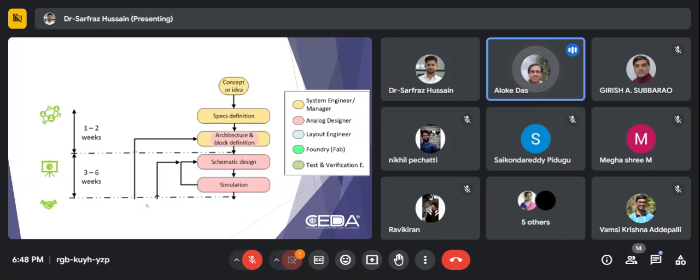And coming back to ADC, there could be a simple ADC, an R2R ladder kind of thing, or it could be a SAR. So if you can do a complicated A to D converter, do it. If you cannot, do a simple A to D converter. It may not be megabit per second. It could be a slower conversion, with lower resolution. Everything is fine. Just do a complete workable thing.